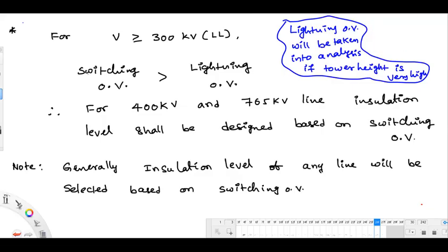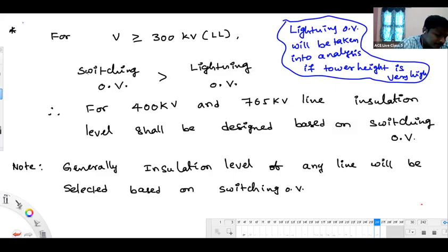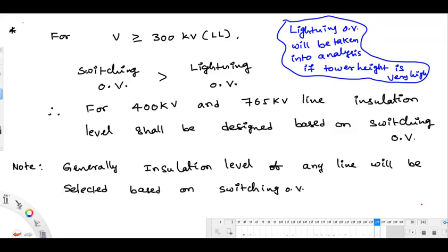Sir, one more doubt I am getting is, when you are taking a ground wire, if lightning strikes that ground wire, it will have current in both directions. Am I right, sir? Yes, correct. Then EMF may be induced in opposite polarities in the power conductor, and that may get cancelled like that. That effect will not occur.